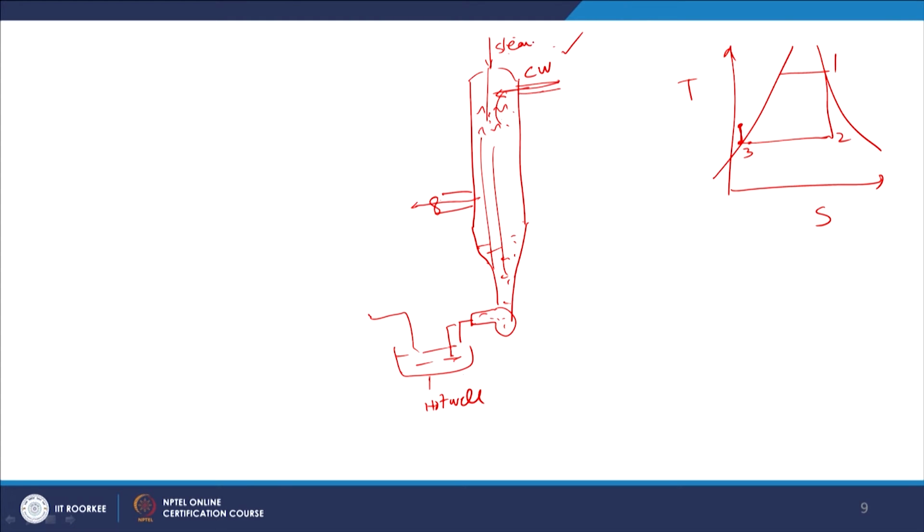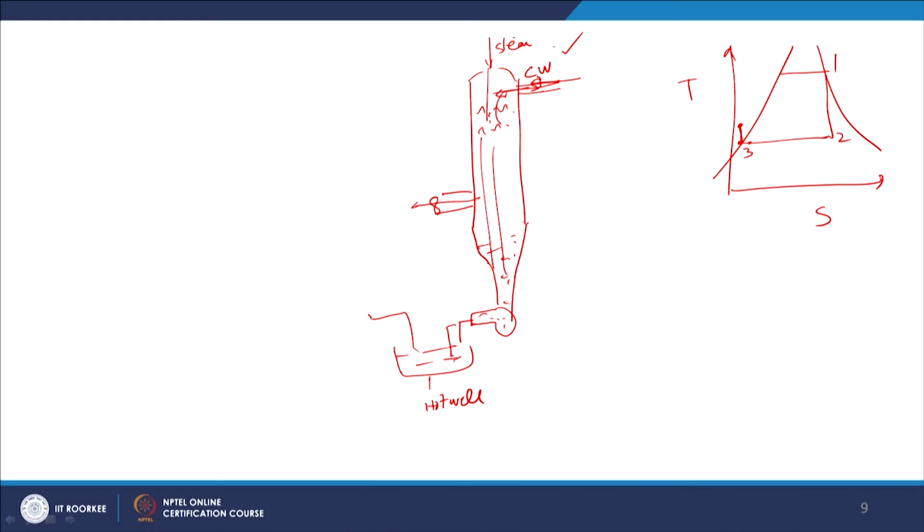But here you see we need extra water. So water has to be plenty. In addition to the other purposes, plenty of water is required here for the purpose of condensation. Now regarding the efficiency, as you know, counterflow processes are often more efficient than parallel flow processes. So here also the parallel flow type of jet condenser is less efficient than the counterflow type of jet condenser. Now these are the low level jet condensers.